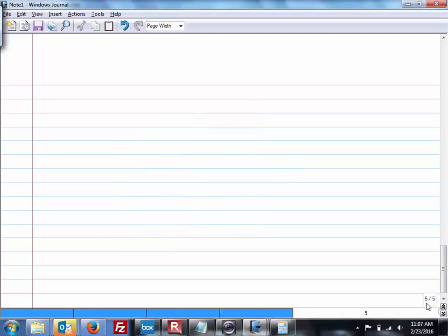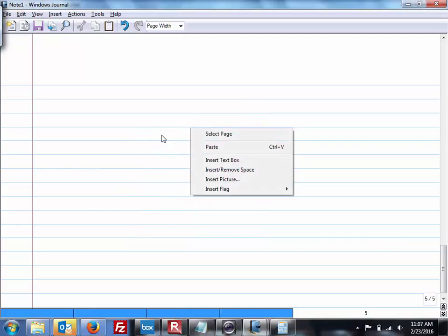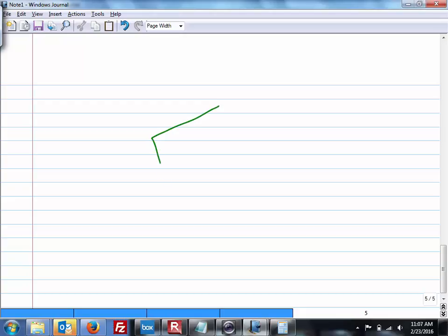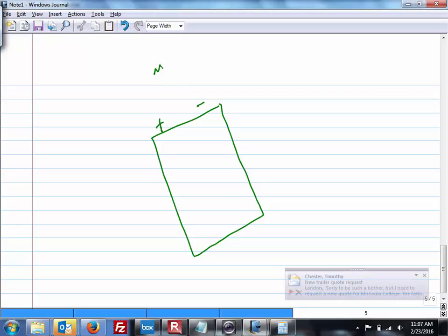Here's your module. There are many cells in series, but what you've got is two electrodes in and out. If there's no load across that, you just put your multimeter on there and measure what's called the open circuit voltage.